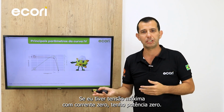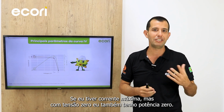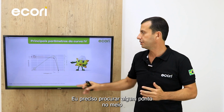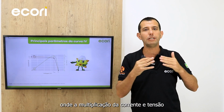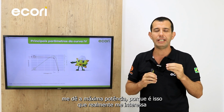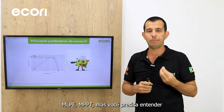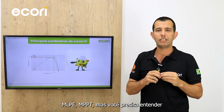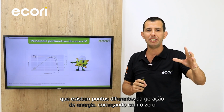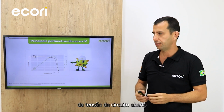If I have maximum voltage with zero current, I have zero power. If I have maximum current but with zero voltage, I also have zero power. I need to look for some point in the middle where the multiplication of the current and voltage gives me maximum power, because this is what really interests me. We're going to talk about this later when we talk about MLPE and MPPT, but you need to understand there are different points of power generation, starting from zero at the I short circuit and ending with zero at the V open circuit.